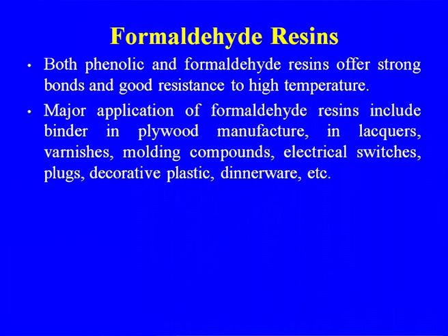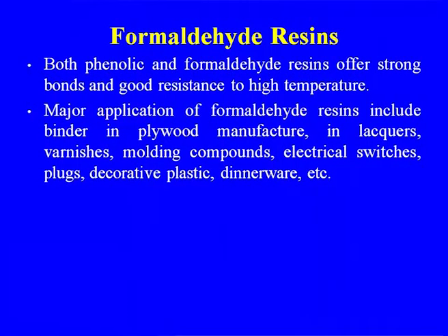Both phenolic and amino formaldehyde resins offer a strong bond and good resistance to high temperature. This is one of the advantages. The major applications of formaldehyde resins include binder in plywood. If you go to any plywood industry, you will find the smell of the phenolic resin. That is one of the major consumers, the binder used in plywood manufacture. Also in lacquers, varnishes, molding compounds, electrical switches.